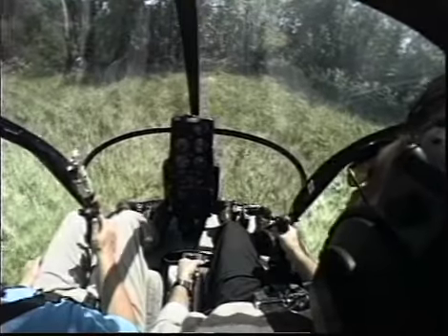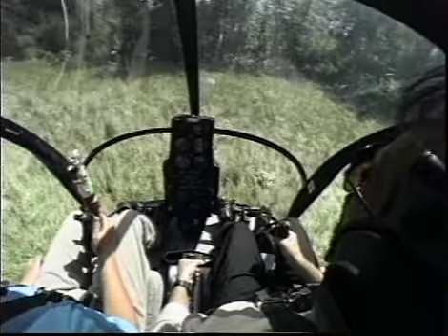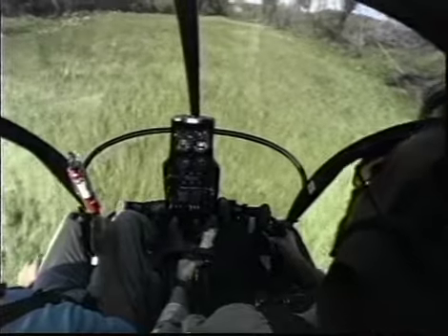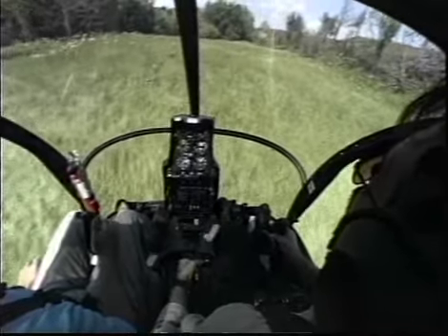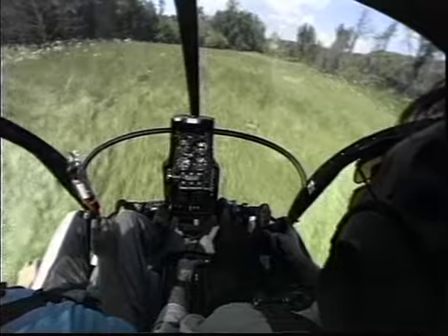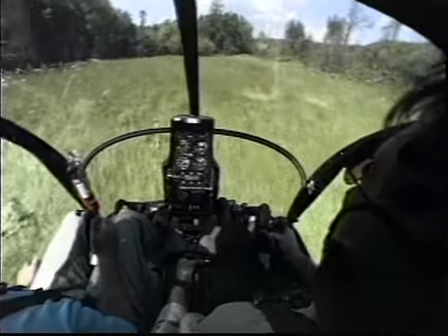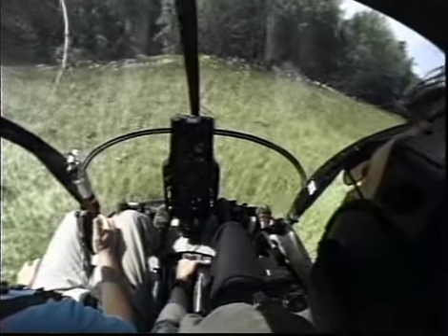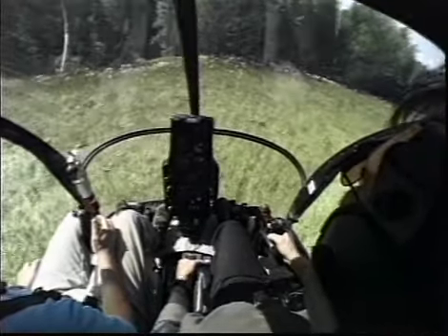Operate the aircraft as close as possible to its normal capabilities. Don't approach any steeper than you have to. Likewise, when departing a confined area, use a normal takeoff from a hover when conditions permit. Obviously, you have to exercise care when operating the helicopter in a confined area. You must be aware of rotor clearances, turbulence, and other such hazards. Use caution when approaching to and departing from a confined area. Plan the flight path as much as possible to take the aircraft over areas suitable for a forced landing, angling into the wind if necessary.